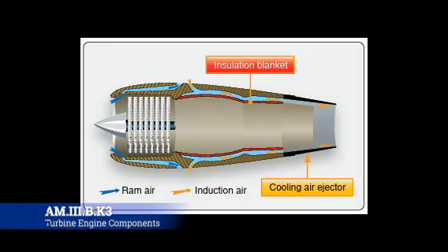Okay, and the last component of all this is the exhaust section, effectively the tailpipe. Now, the exhaust section is really going to come down to one thing: it's just heat management. If you look at this graphic, you'll see we've got ram air coming here to help cool things off, kind of like an augmenter of sorts. You'll have induction air there, and insulation blankets to keep the heat from leaving the engine and getting onto the airframe. Very important, you'll see on the inside of cowlings there's asbestos insulation that will prevent any sort of superheating or spark translation over onto the rest of the airframe.